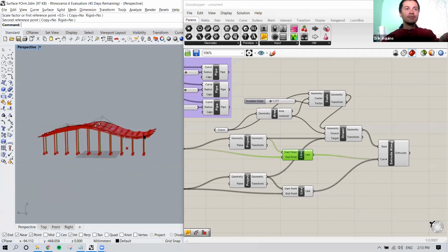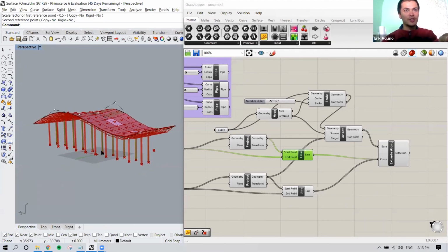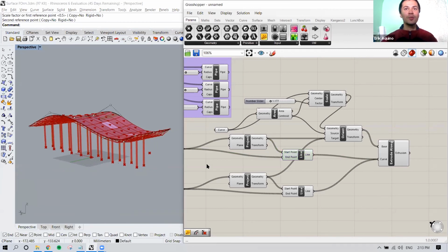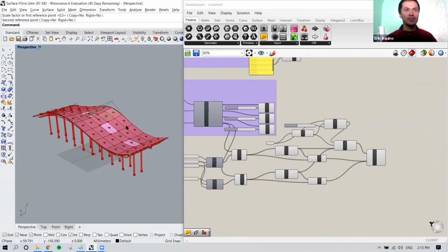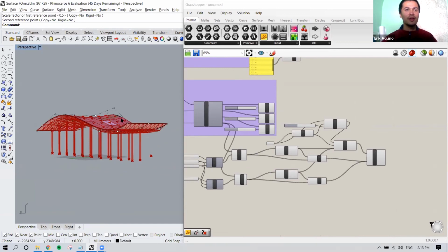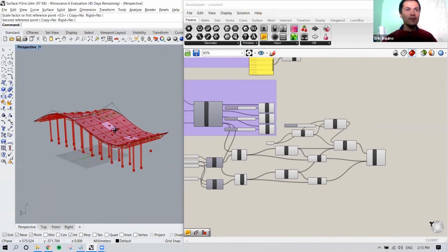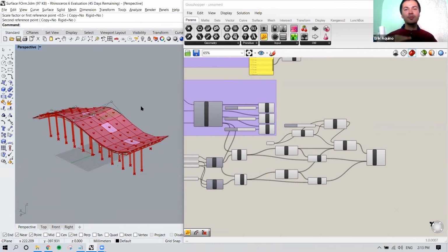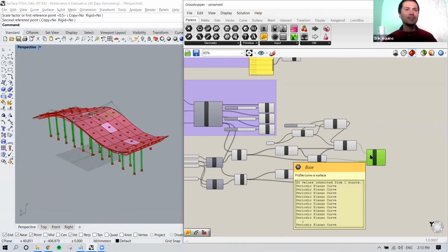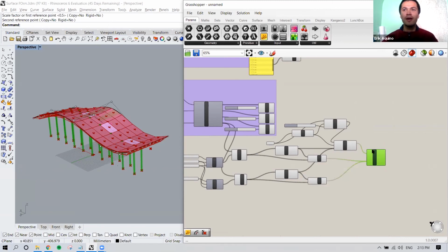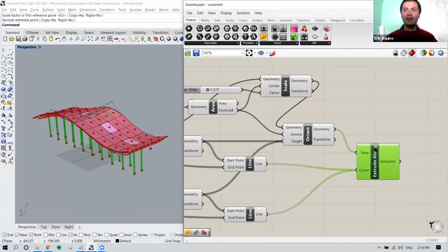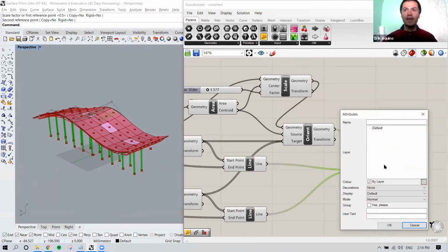Right. And that's all I basically wanted to show you guys. When you're baking your components into Rhino, so just exporting or importing it from Grasshopper to Rhino, I would suggest making the layers beforehand. Otherwise, they'll all just go to the same default layer. So I don't think we've shown it in a tutorial how to bake, but it's really simple. So these are my components that I'd like to bring into Rhino. Right click on the middle portion, bake, with that little egg icon.